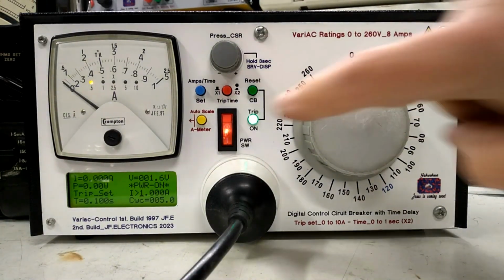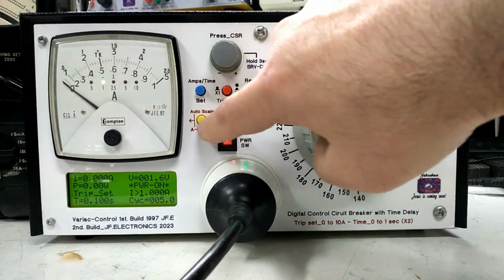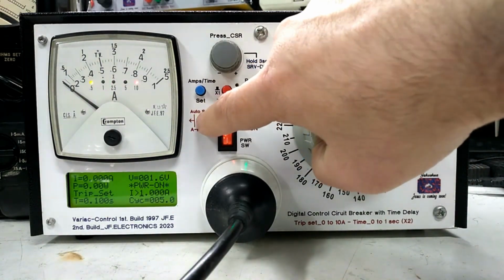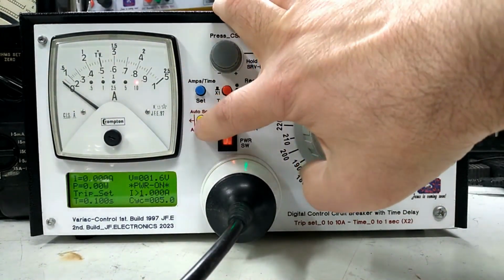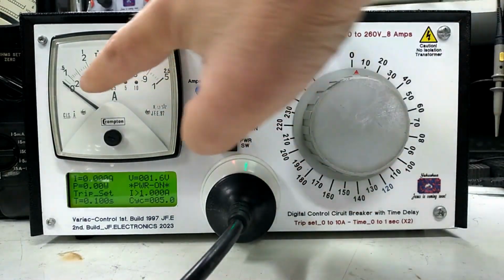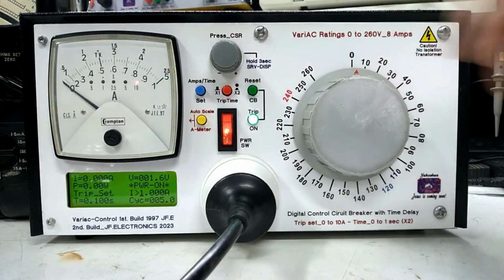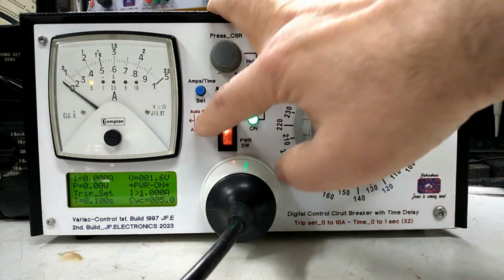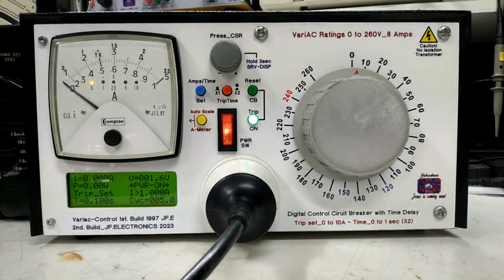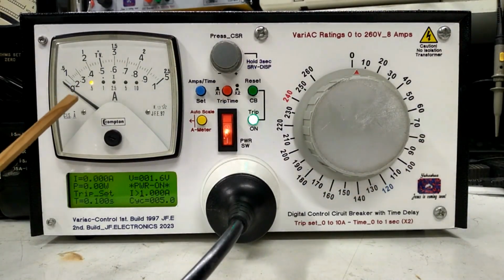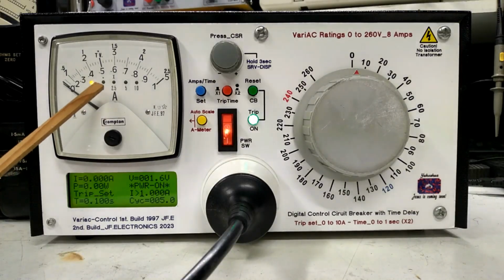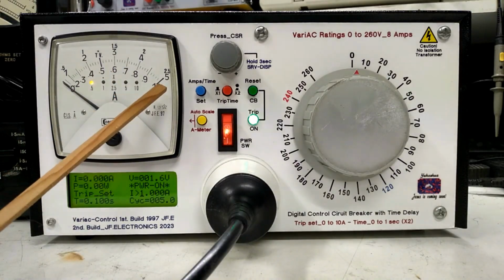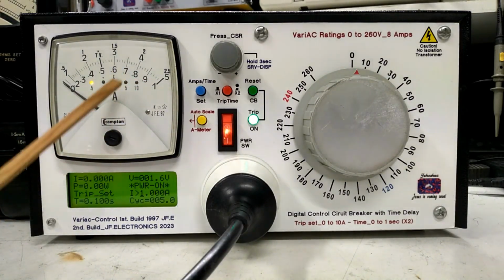And so this yellow button here changes your scale. Okay, so for example, that's a manual. I'm changing the scale of the analog meter manually. And so if I've got it on the 0.5, which is the lowest scale, once it goes over 0.5, it will jump to 1 and to the 1 amp scale. And when the 1 amp scale has reached the limit, we'll jump to the second one.